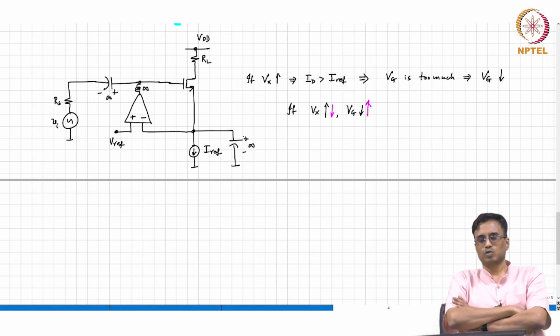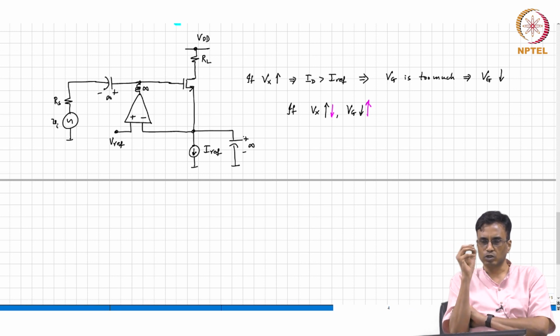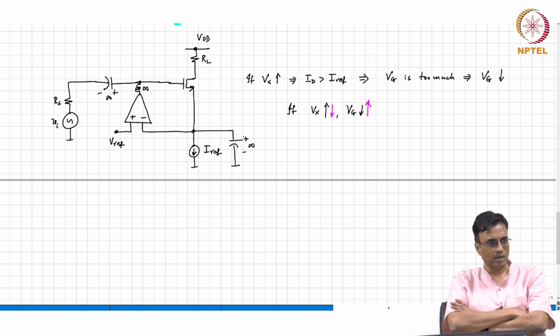Current will flow. So basically, if the input resistance of the voltage controlled source is not infinite, then it will draw some current which will disturb the voltage that is being monitored, right? You don't want that to happen. Therefore, the voltage controlled current source must have an input resistance of infinity. And what about the output resistance of a voltage controlled current source? It's a current source, so the output resistance must be infinite.